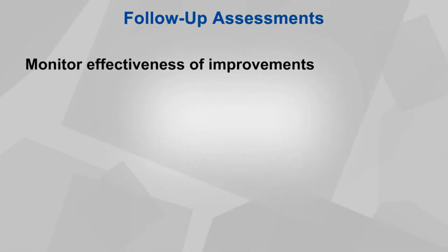We get outputs like lighting improvements. Replacing incandescent bulbs with LED lighting can significantly reduce energy consumption. Installing motion sensors and daylight link controls can further enhance lighting efficiency by ensuring lights are only on when it's needed. HVAC system optimization. Ensuring that HVAC systems are properly maintained and optimized for efficiency can lead to substantial energy savings. This might involve installing programmable thermostats, sealing ductwork, and upgrading to more efficient units.